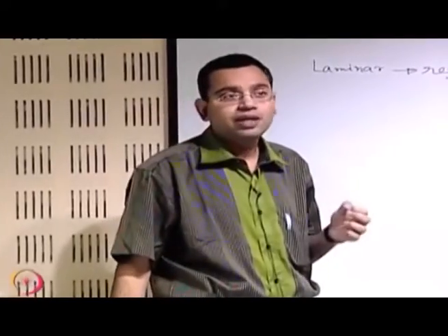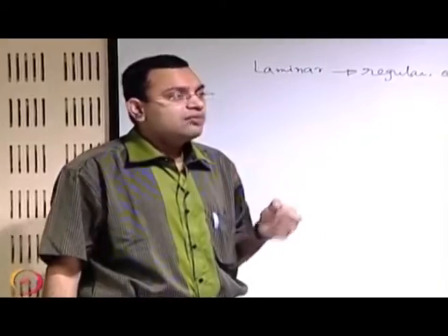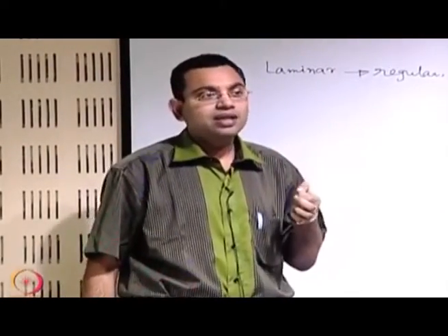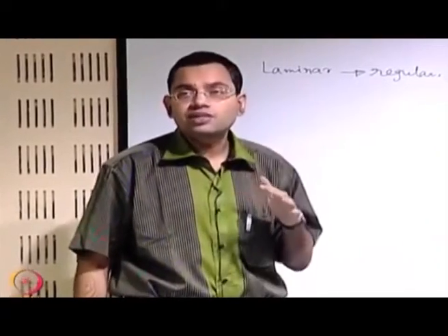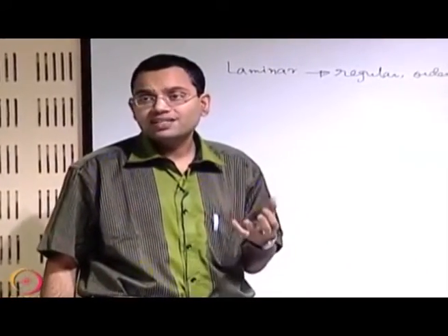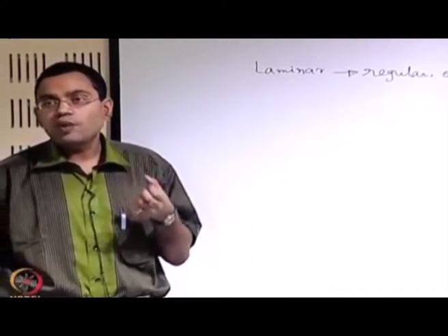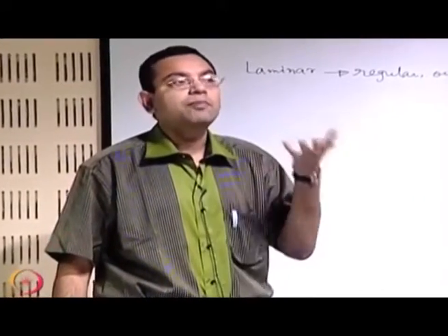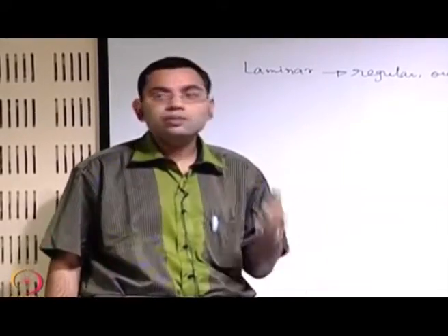That is very important. That means if you have a slight disturbance, then even at a very high Reynolds number the disturbance may get absorbed, but if you have a very high disturbance or even a moderate disturbance, then in a high Reynolds number case it will be a turbulent flow. Whereas if the Reynolds number is somewhat low or very low, then no matter how large the disturbance is, the disturbance will not be amplified. It will go to a stabilized situation where the disturbance dies down.